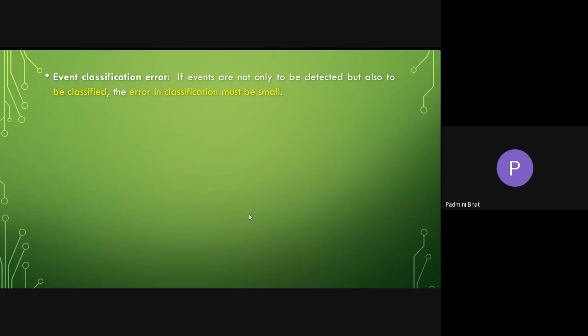For example, different kinds of alarming: it may show a yellow light for a slight danger level and a red light for high danger, so that every person in that area has to vacate, maybe for toxic gas leakage. If for a moderate level, instead of the yellow light, it gives the red light, then every time the people will be vacating the places, which is not required because the level was not so high.